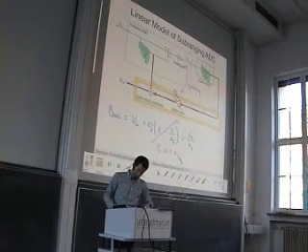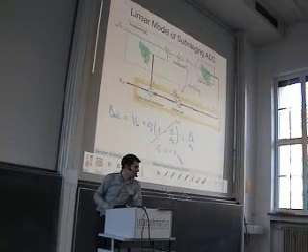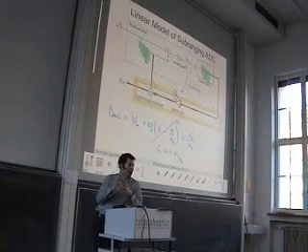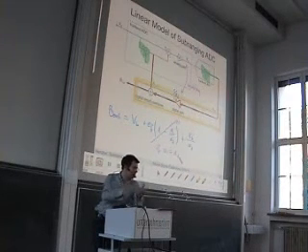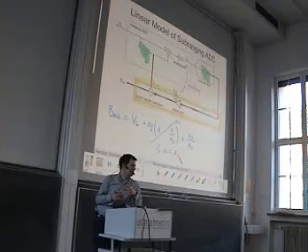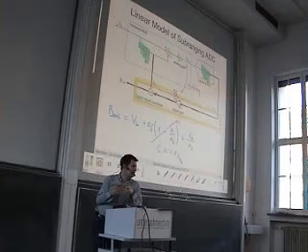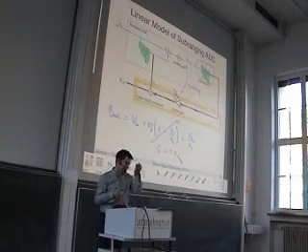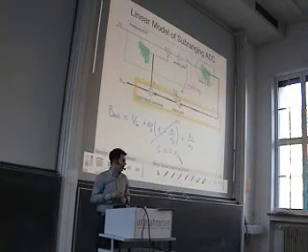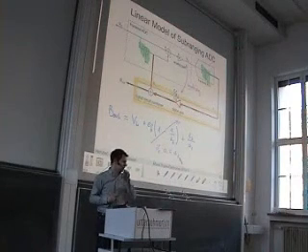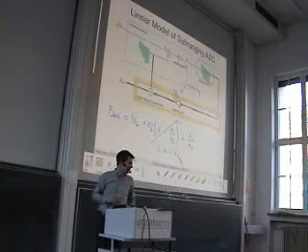Well, what happens if we go from 2 stages to n stages? So here we had a front-end ADC and a back-end ADC. Now you can say, okay, let's do the same thing for the back-end ADC. Subdivide the back-end ADC again in a front-end and a back-end. And the resulting back-end can be subdivided again in 2 ADCs.